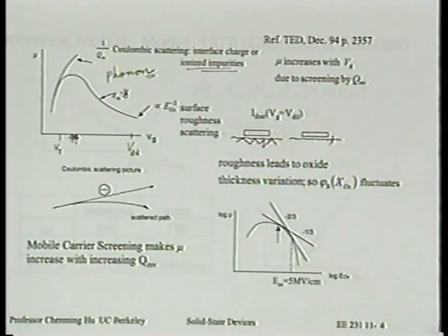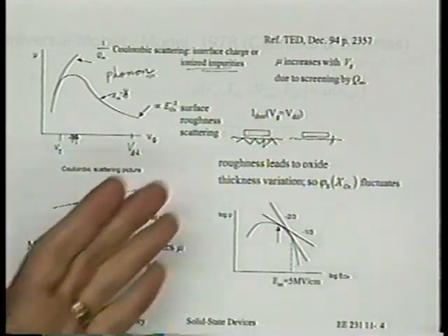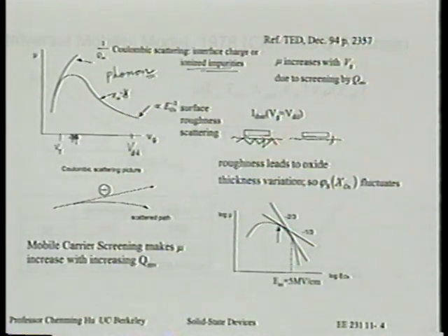But it's very important to remember that if we're talking about a good SiO2 and silicon interface, everyone's getting the same mobility today. Now, there are very rare exceptions to that, and it's believed that the most likely way to create a non-standard mobility versus vertical field behavior is nitridation. So let me not get into that. It's generally agreed that nitridation will change this curve. But other than that, if it's an SiO2 silicon interface, the fact is that everyone has been getting the same mobility and is still getting the same mobility right now.